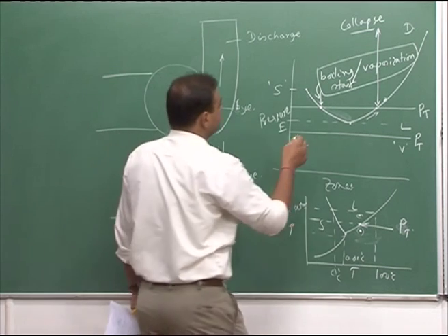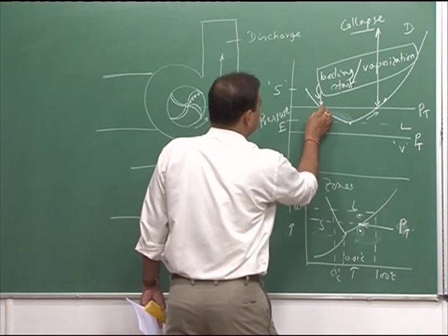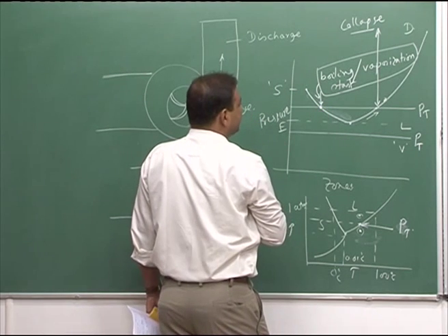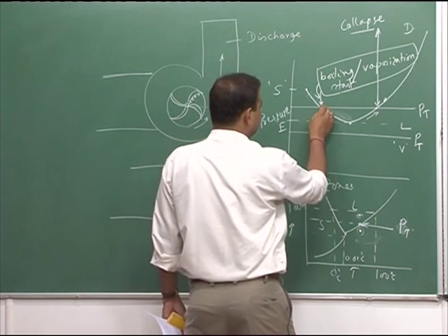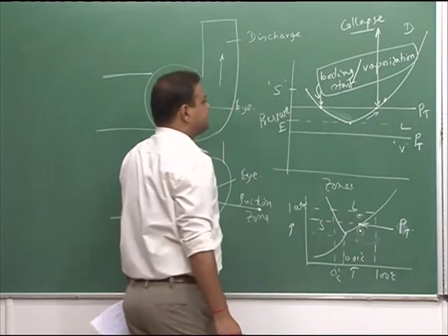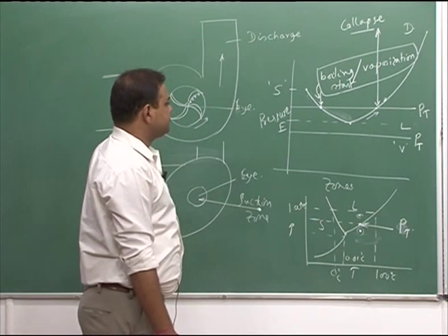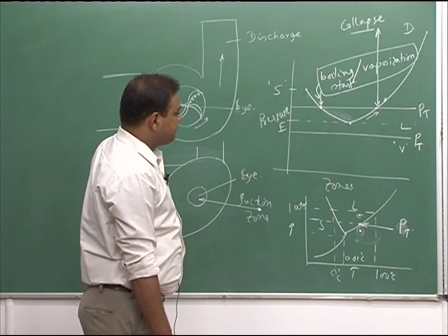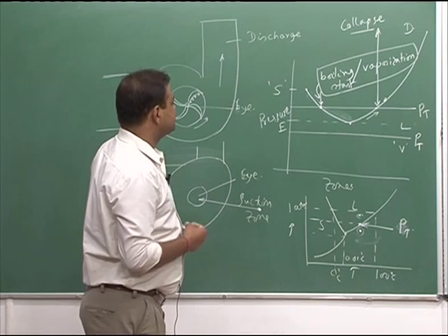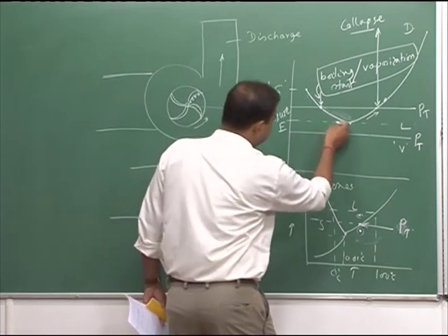So, that means here cavitation starts, that means bubbles start forming, because the pressure is going down and it is less than the equilibrium pressure needed at that temperature to form bubbles, and the boiling would keep going on.